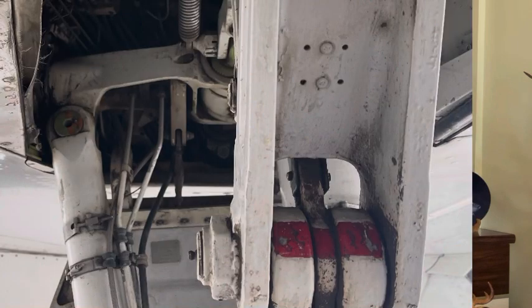In the main landing gear we have three red strips. When these three red strips are aligned, this means the landing gear is fully down and locked. For the nose landing gear we have two arrows, and when these two red arrows are aligned, this means the nose landing gear is also fully down and locked. The viewing port for the nose landing gear is in the cockpit, just past the cockpit door, and the viewing ports for the main landing gears are inside the cabin.